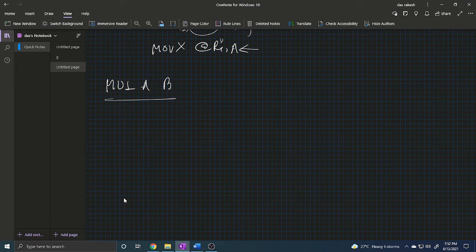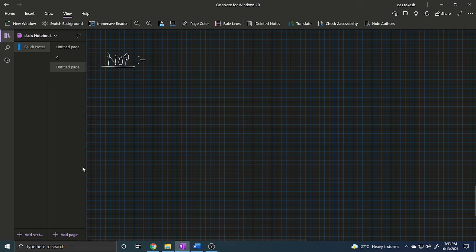Okay, so this is a move related instruction, and different types of arithmetic and indirect and direct addressing modes are discussed here. Now the next important instruction, for delay operation, is NOP, no operation. It performs no operation, and execution continues with the next instruction. It's sometimes used for timing delays to waste clock cycles. So NOP means no operation, and that's why it is very important for delay generation programming.